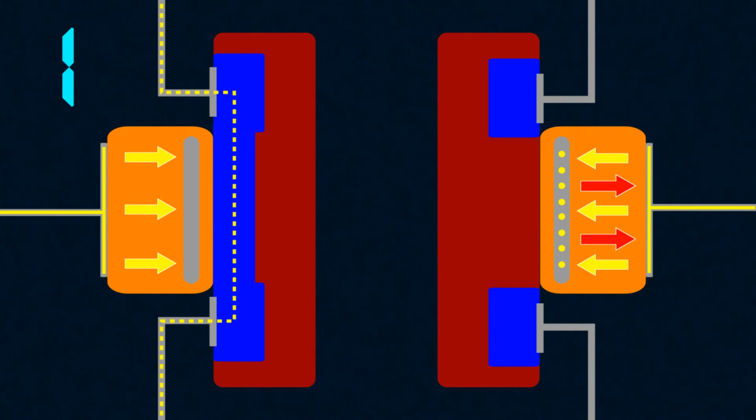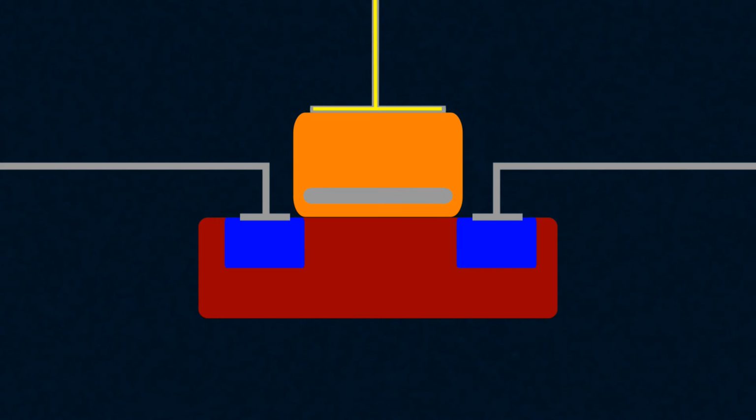If electrons are present, then at the same voltage, the transistor remains closed, no current flows, and we say that a 0 is written in the cell. So essentially, we've described how the read operation from a memory cell consisting of a floating gate transistor will look like.